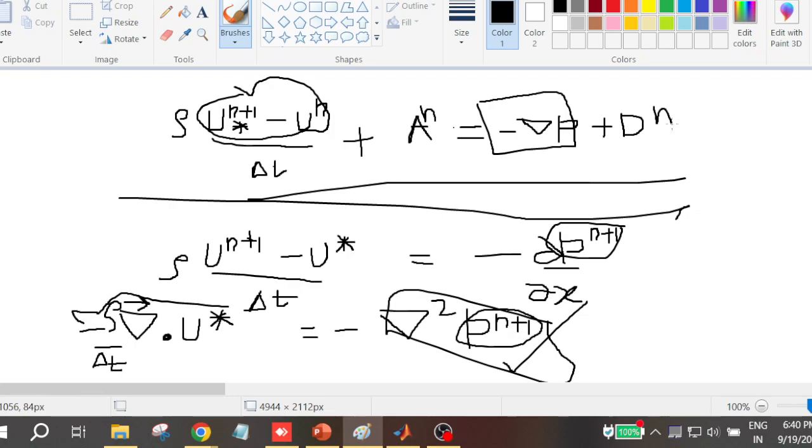In the weekly content, I saw that it was given as explicit, but it is neither explicit nor implicit. It is called a semi-explicit scheme. This particular scheme is not explicit, not implicit, not Crank-Nicolson. It's semi-explicit. Why? Because you are taking all the terms except the pressure at the n time level. So in that regard, it's an explicit scheme. But you are not taking pressure at n. You cannot take it also because they are coupled in a sense. You will get a false answer. So it is usually called a semi-explicit pressure projection scheme in literature.